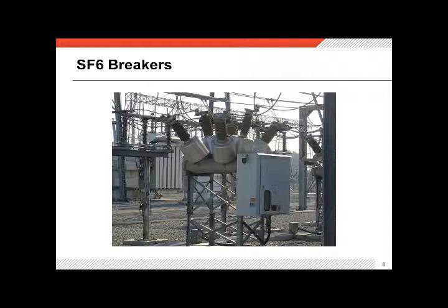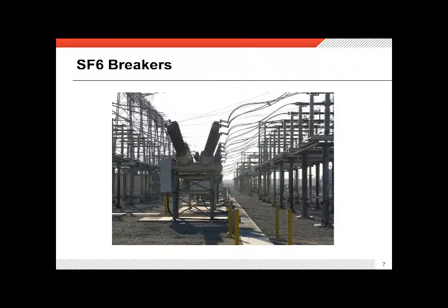So anyway, let's go ahead and look at a couple more circuit breakers. This is actually the same substation, a different voltage class, and this is a 230 kV. And you see disconnect switches on either side. There's your control cabinet. There's the cylinder that has the interrupters in it. Here are your bushings. And there's the cowling under which you'll find all of your current transformers.